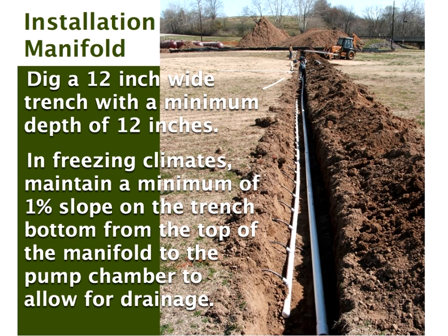The sand mounds, particularly if you feed them with drip. Most sand mounds are not fed with drip, what they call Wisconsin mounds, and they work just fine. Usually, though, unless people are very careful in terms of the ability of the soil underneath to actually absorb the amount of water being put into the mound, they will break out at the foot. But again, if it's correctly designed, it'll be clean water.